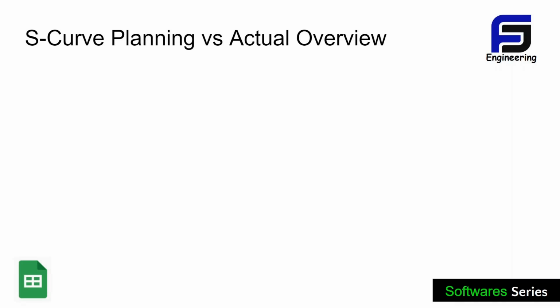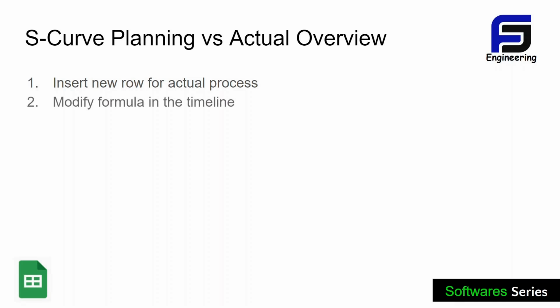Alright, here is the overview regarding step by step to create S-curve planning versus actual. First of all, we will insert each process for actual process, so we can copy planning process for actual process. After that, we are going to modify the formula in the timeline so we can get the value for the actual process.